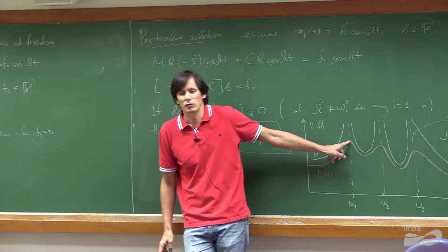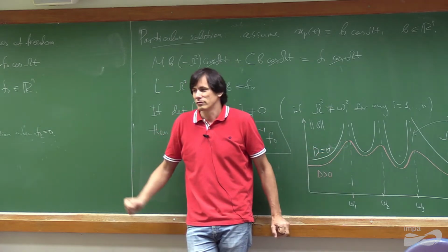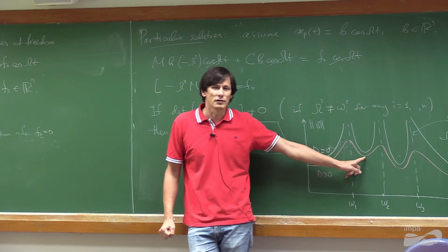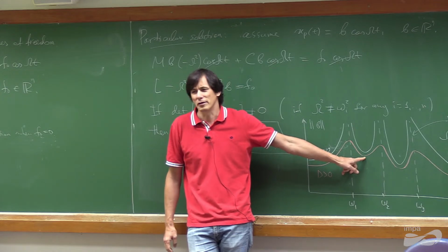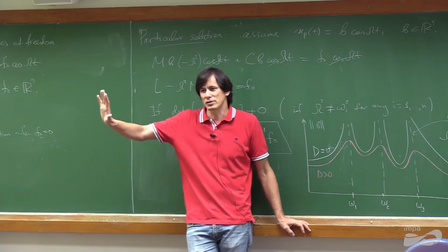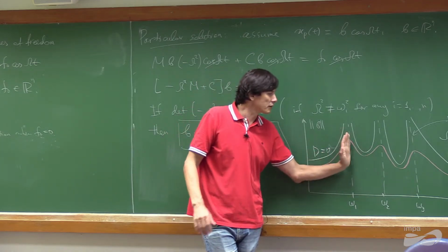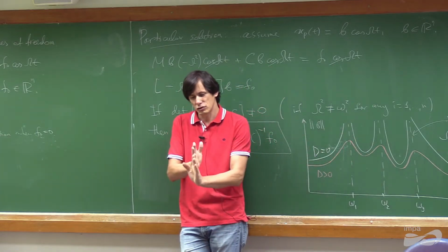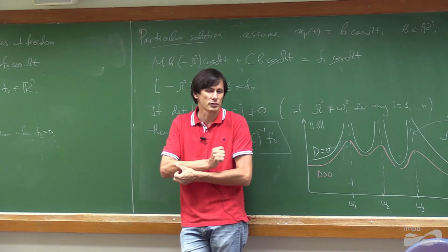The way you avoid it is you move the window and you get out of the resonance, and then it stops making the noise. Or if you press the window, you also shift eigenfrequencies, so the frequency of the forcing just should not be close to one of the eigenfrequencies.